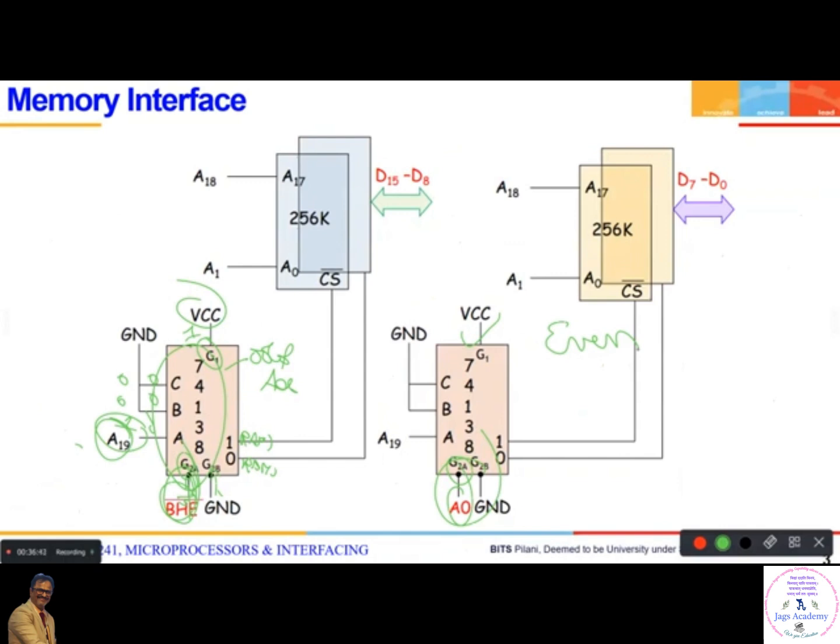I have understood this. Now, depending on my previous topic, can you convert this entire diagram using only one decoder? Only one decoder. How to convert this into one decoder? Tell me. But what to do with this bus enable? Directly ground this. Okay, this will not be there at all. Then you do the same arrangement using OR gates.